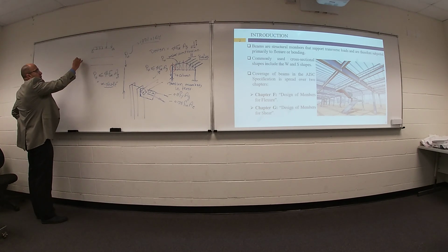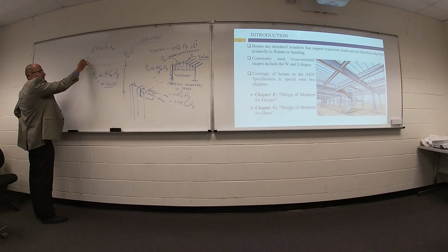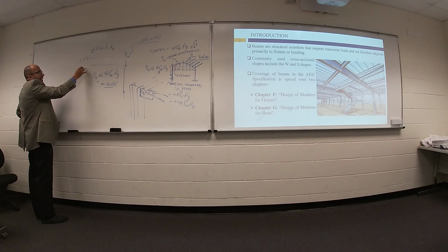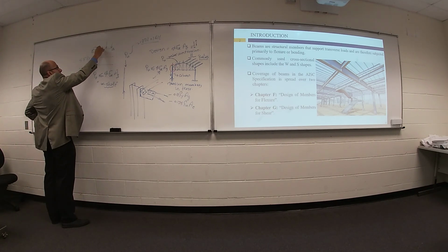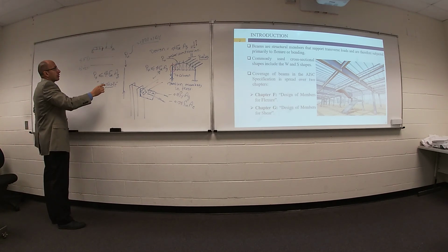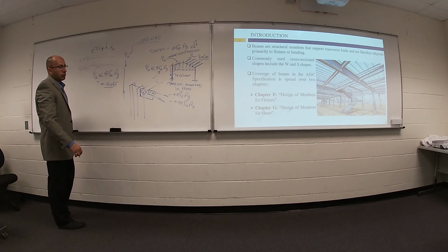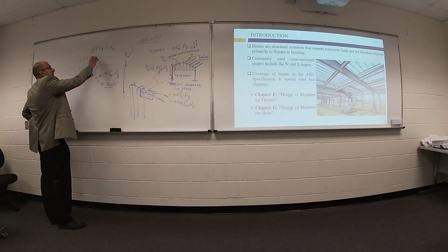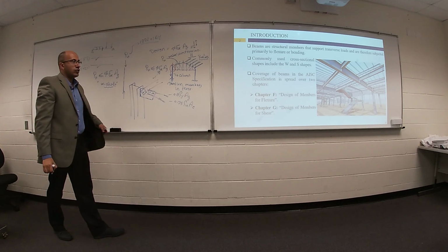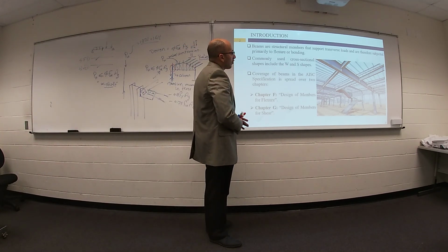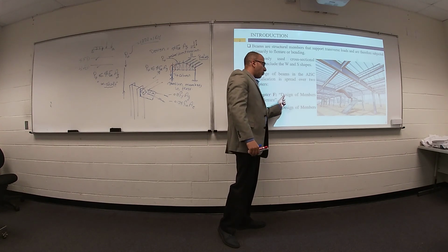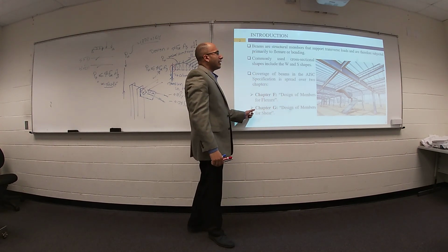The first one called shear force diagram. The second one called bending moment diagram. So your beam must support your bending moment, which called flexure, and your shear force. So if you are talking about design of beam, we need to satisfy the applied moment and the applied shear.